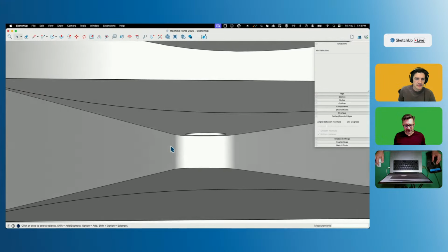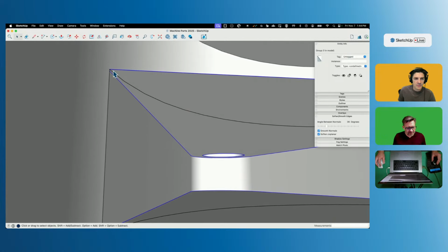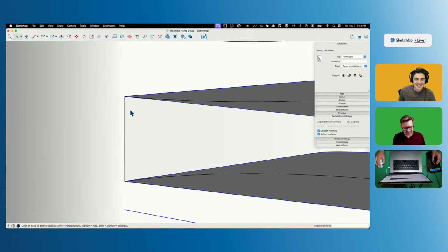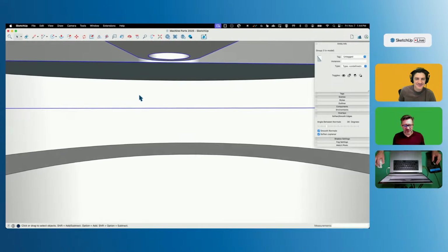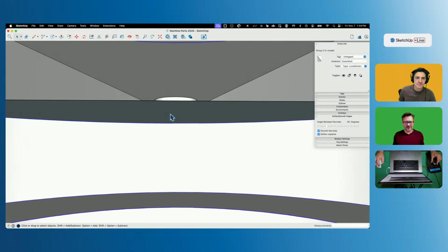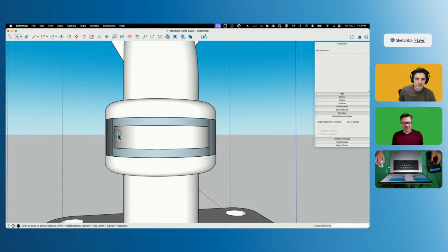So the issue that I'm hitting right now, the reason that's not, oh, look at that. It's just short. Oh my goodness, look how cute that is. It's so off. So what I can do, sometimes this happens when I'm intersecting faces, I cut one back and it's just, I don't know, just shy of where the other one is. So I need to manually copy those intersecting edges.